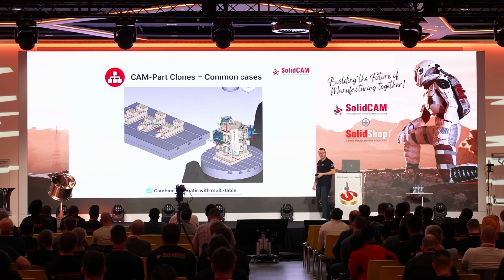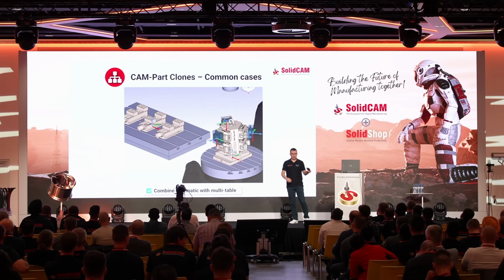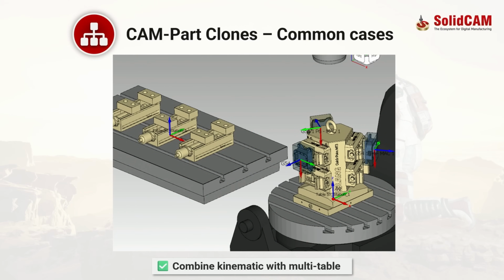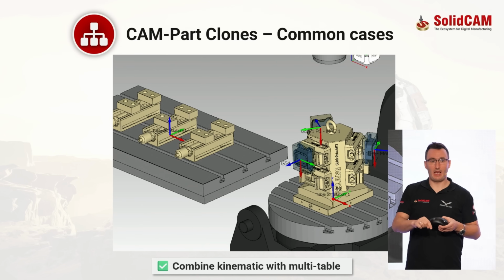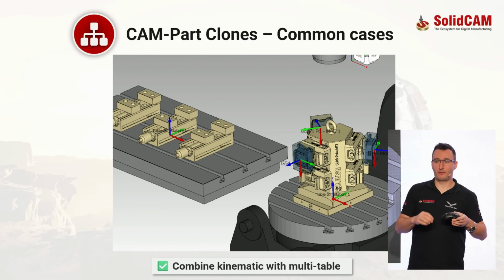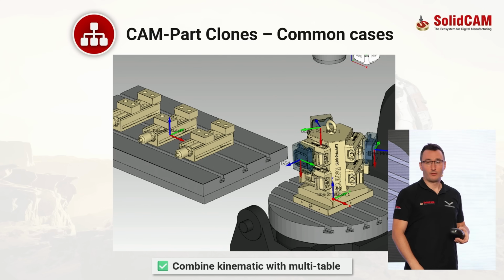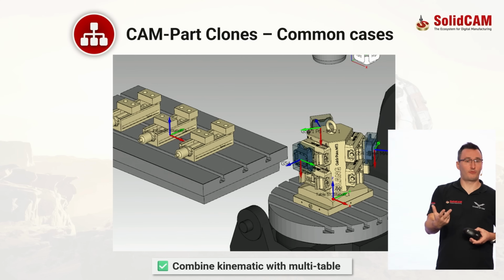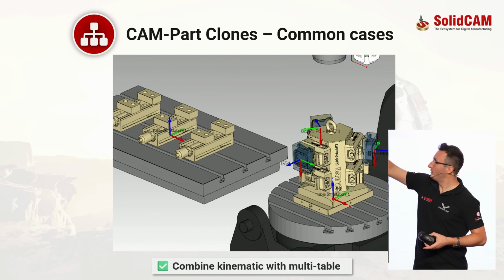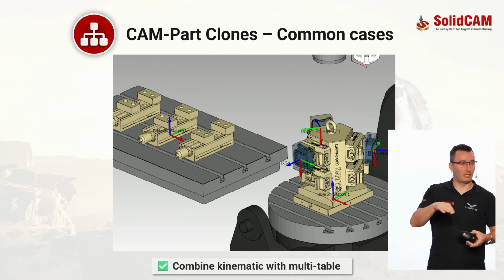We also can do a combination. So what I told you about the clones, and what I told you about adding the new workpiece, you can combine these 2 features. So this is the example. Over here, I will define 1 master workpiece and 2 clones. Okay? I will machine the first side, and then I will use the option of add an MCO, make a part transfer. I call it part transfer. It will be an operator that will move the part there. Second side, right? So in this program, I will have the 3 MCOs that will move each of these individually there, add new workpiece 3 times in the channel synchronization.